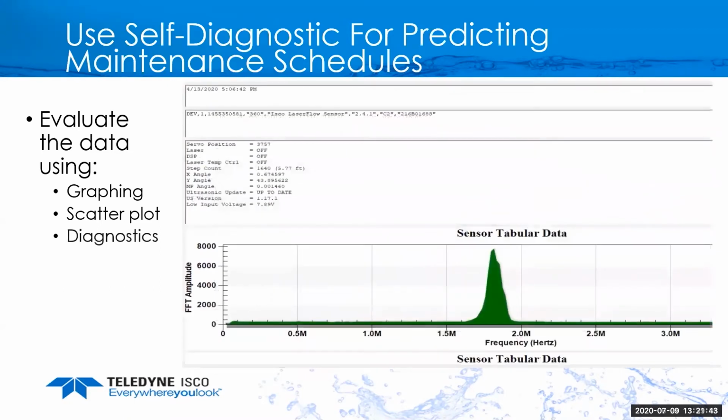One of the big things, and this is one that I look at all the time, is the diagnostics that we get back from a meter. In this case, this is a laser, which is what I'm obviously most familiar with. The bottom axis is the speed of the water. In our case, when the laser takes a reading, it takes 5,000 scans in about 2 seconds. For every reading that reflects back, we transmit a known frequency and get the return frequency shift. The more that agree, the bigger this signal looks. So when I look at this, I see a frequency of roughly 1.7 meg, which is about 1.7 feet per second. The more that agree, the bigger this signal is. On the left, it says FFT amplitude. You'll notice that is in the 8,000 range.